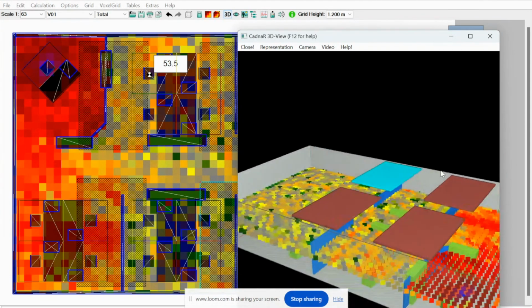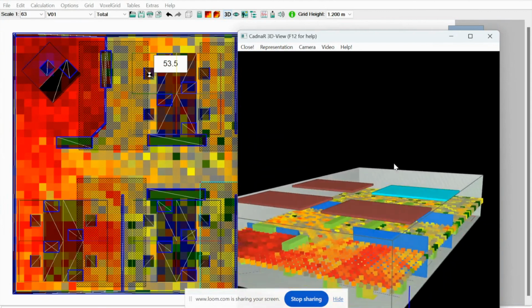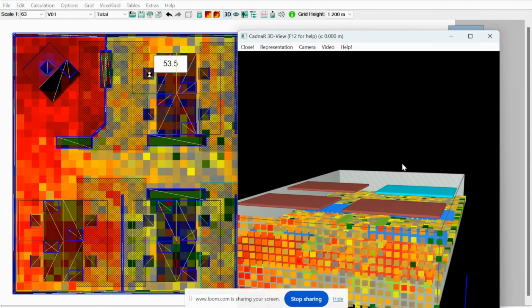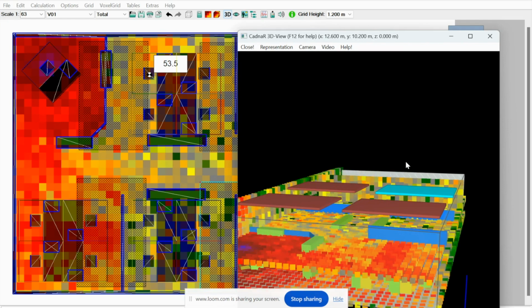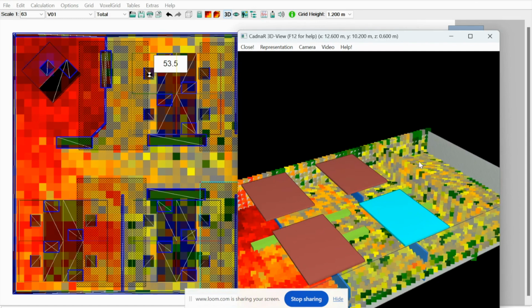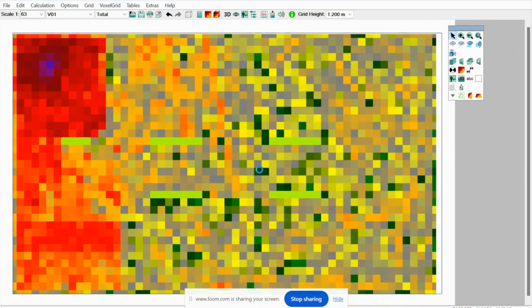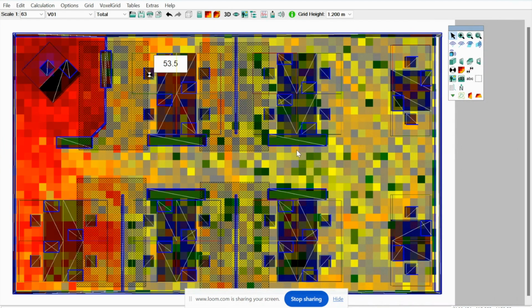Plus, you can see it makes these boxes bigger, so we start to fill that out. Press the X and you can see it moves in this plane. If I hit the Y on my keyboard, it's in that plane, and Z moves it up and down. So we've got color contour maps to show the dispersion of the sound levels around the room. And we can also do that for sound STI and so on, and reverberation time and individual third or octave bands, frequency bands. Okay, so that gives you an idea of how quick it is and how flexible it is to use for the modeling.